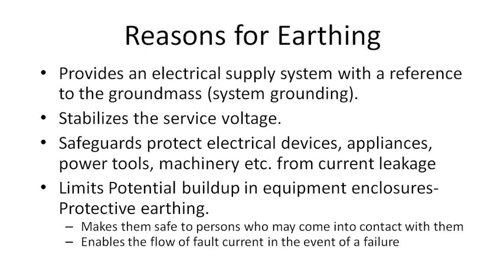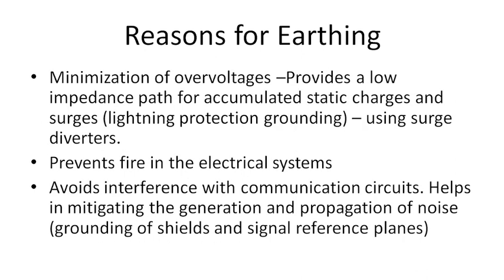And the next point is it safeguards the protective electrical devices, appliances, power tools, machinery, etc. from leakage current. So it is related to protective earthing. It also limits potential buildup in equipment enclosures, so that it will be safe for the persons operating that particular device when they come in close contact with it. And protective earthing also enables the flow of fault current to the ground in the event of any insulation failure. So these are the various reasons behind earthing.